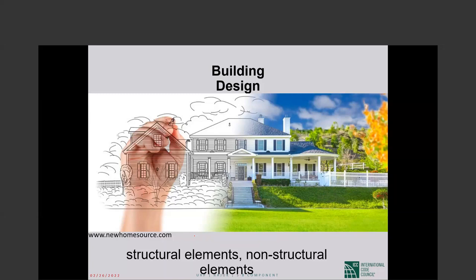or what we do in designing a building: usually there are many elements in a building. We classify those members as load-bearing elements. Some of the load-bearing elements carry the gravity loads, vertical loads, some lateral loads. So these are the main point for us in design, designing these load-carrying elements.